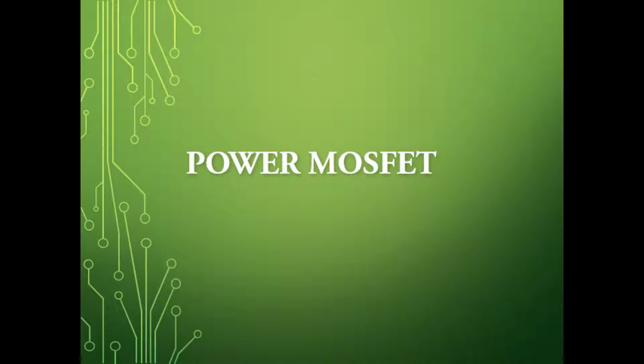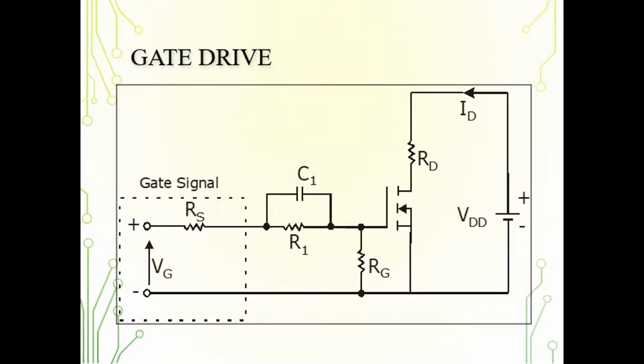Hello everyone. In my previous video you have seen the switching characteristics of power MOSFETs. If we want to achieve a higher switching speed, we need to reduce the turn on time and turn off time of the power MOSFET. So if we want to reduce the turn on and turn off time of the MOSFET, we can include an RC network in the circuit.